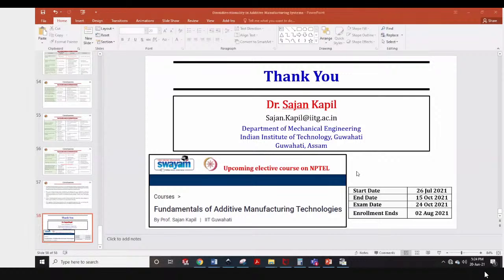No, sir. I'm telling that I'm depositing a wall in 3D. Suppose I'm doing one deposition and making a component, depositing in Z direction. In one direction you will not have any issue. What I can do is move the torch in one direction, return back, and again move in the same direction, tracing the path and starting again from the same point. You are right. No issues will be there.